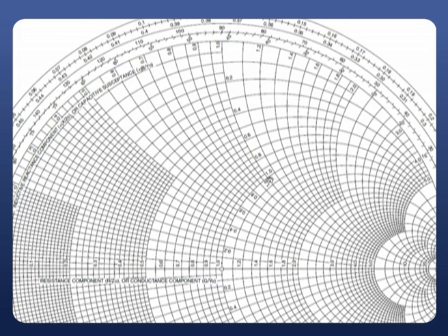The first and most important step is to get the ZL location, and I am assuming that this is the ZL location, 1 plus j1 ohms is the ZL. Now the second step is to draw a straight line from the center point to ZL and extend that line up to the R equals 0 circle using a scale. Just draw a straight line passing through ZL from the origin to the R equals 0 circle. This particular line is enough to calculate our gamma.